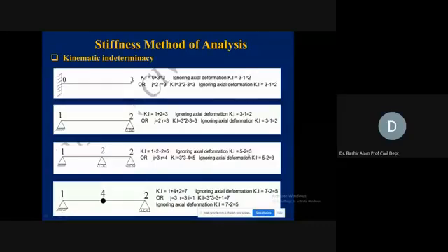And what are those 3 degrees now? It will be rotation at 1, rotation at 2, and rotation at this final support, which is to the right. We are ignoring the axial translation in the middle support and at the right support. So only rotations we are considering. Why rotations? Because the axial effect, the bending stresses will be more in case of the beams. By using the equation now, joints we have 3. Reactions we have 4, 2 from the left support, 1 and 1 from the middle and right support each.